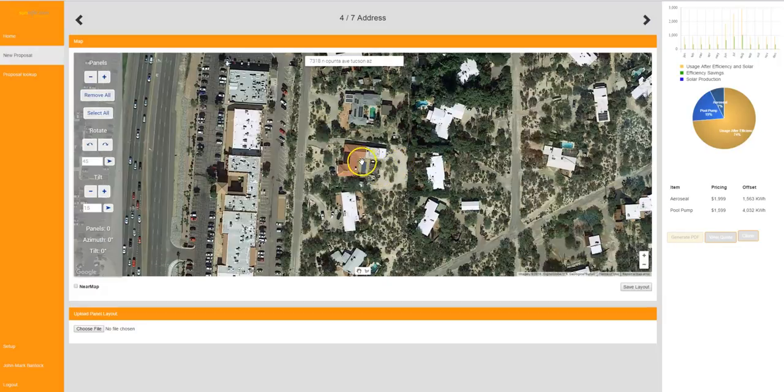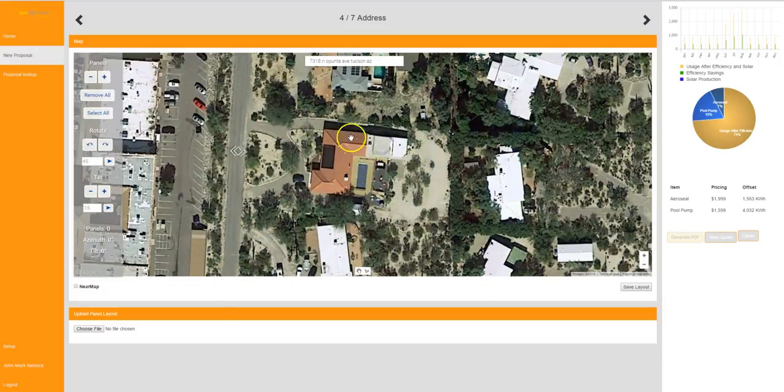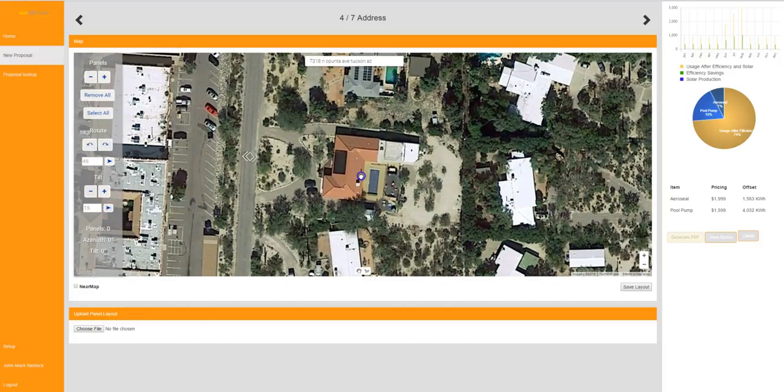Next step is laying out the modules. Our design interface is fairly simplistic at this point, but we are working on numerous upgrades that will allow you to automatically map panels onto the roof. In this current version, you can simply add in modules, and you can highlight them and use the A, S, D, and W keys to add in modules around that one if you so choose.